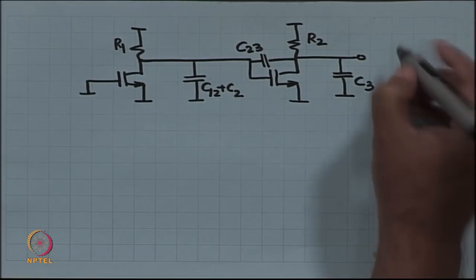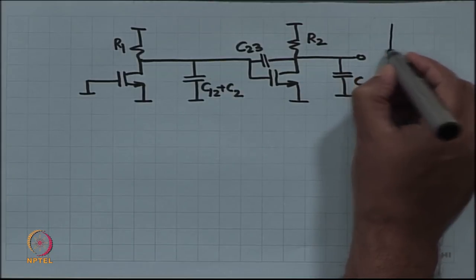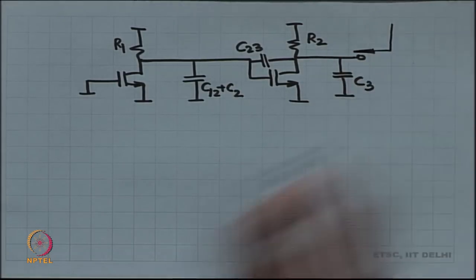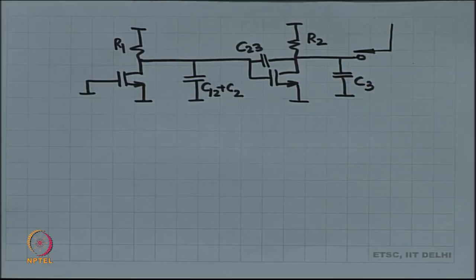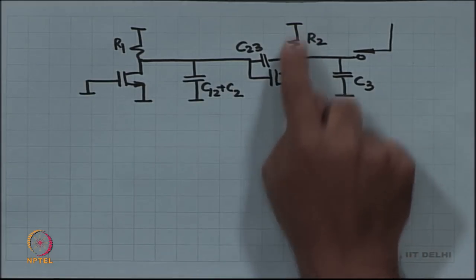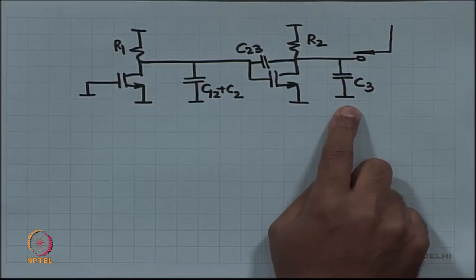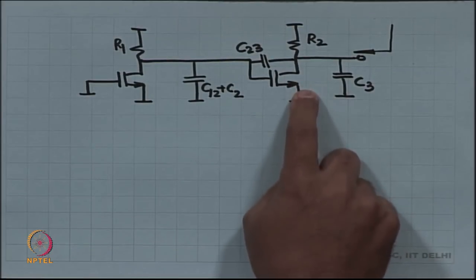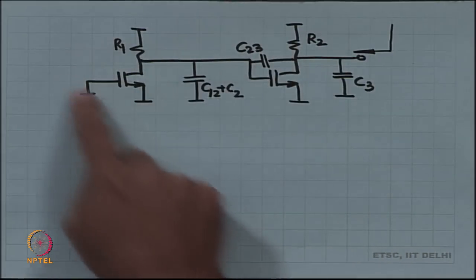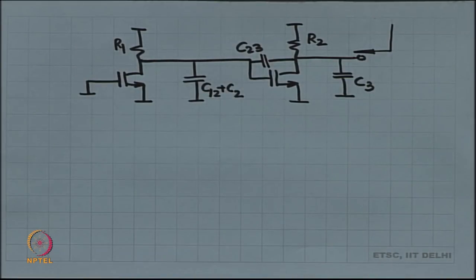All right. So, we are going to now find the output impedance looking in from here. What is so hard about this? Is this hard? You look in from the output, you see R2 and C3 and maybe RDS2, right. What about all of this stuff? Does it matter?